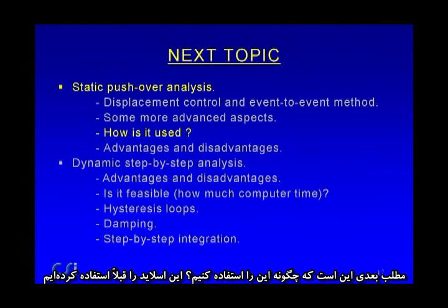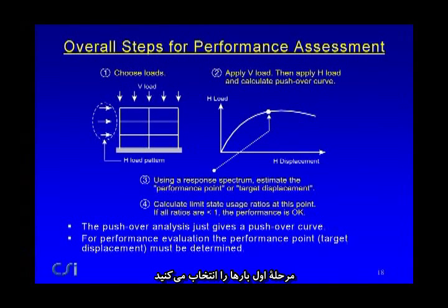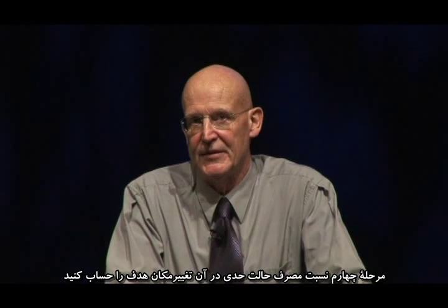Next event, how is it used? And we used this slide before. Step 1, you choose the loads. Step 2, you get the pushover curve. And then step 3, using a response spectrum, you estimate the target displacement. And step 4, you calculate limit state usage ratios at that target displacement.